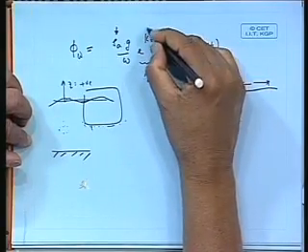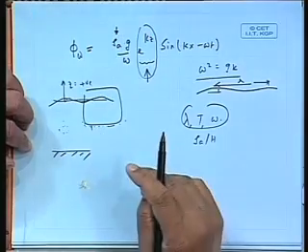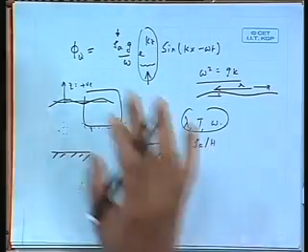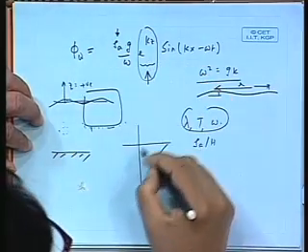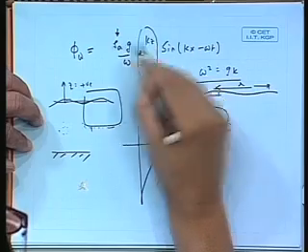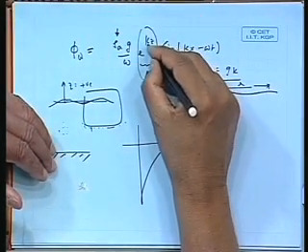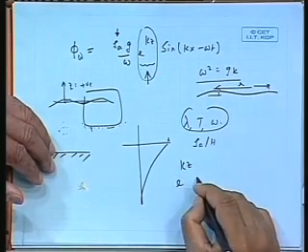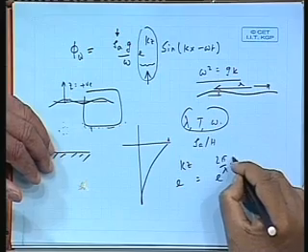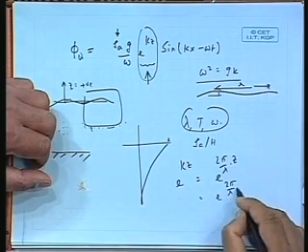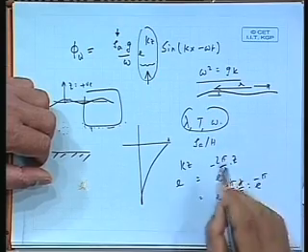Now, it turns out that this relation tells me every parameter has a decay with respect to kz. If you plot this against kz, it will look like this. I will come to this at more length, but what it means is that, supposing I try to find some parameter phi here, if the value is 1 unit at z equal to 0, and when you give z equal to minus 5, this will become e to the power of minus kz, much lower. In fact, if you keep going down, take k as 2 pi by lambda, and z is some depth. Supposing you look at a point about half the wavelength deep, that means z is lambda by 2. So, what happened in that case? This becomes e to the power of 2 pi by lambda into lambda by 2. It is e to the pi, minus pi, there is a minus because z is negative. Now, you can calculate yourself. E to the minus pi will become equal to 0.004.